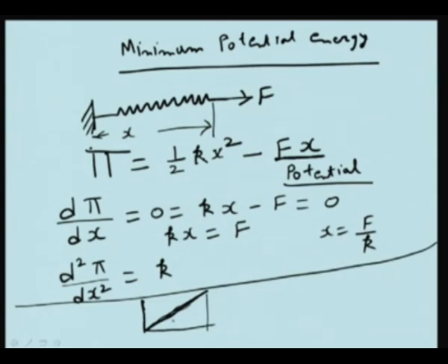So in this case, the work done will be equal to half Fx. This work done on the spring is stored as the potential energy of the spring. The potential energy of the spring increases because the external force is doing work against the conservative force field, that is in the opposite direction, minus kx.